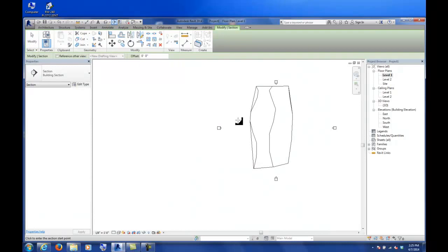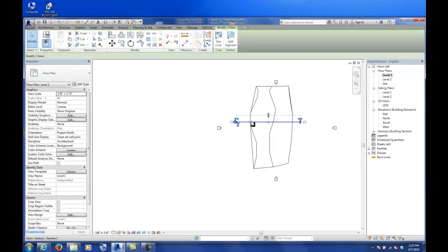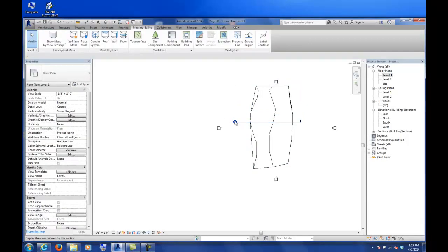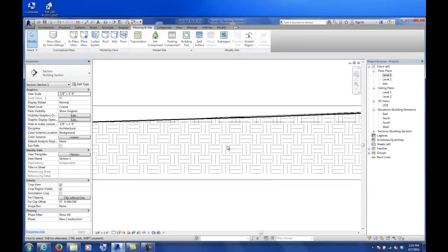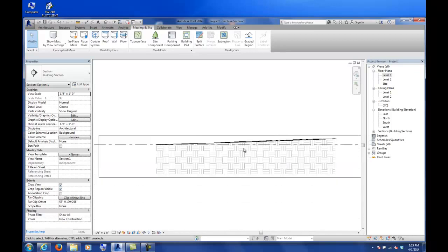Is that when I cut a section, let's say I was cutting a section through my building and so on, you will get the kind of classic hatch pattern that's associated with drafting ground already generated based on wherever the topography surface is, where you're cut, and so you'll see this cut line is pretty dark up there, and then you've got this topo surface, or the kind of hatch pattern that's associated with the ground, and that's going to change based on what scale you're at.